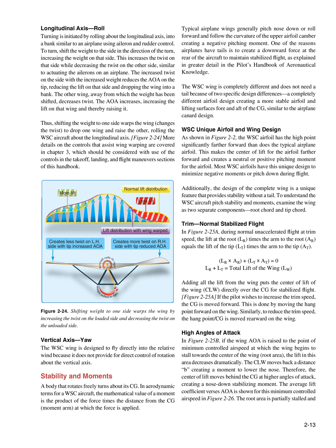Vertical axis, yaw. The WSC wing is designed to fly directly into the relative wind because it does not provide for direct control of rotation about the vertical axis. Stability and moments. A body that rotates freely turns about its CG. In aerodynamic terms, for a WSC aircraft, the mathematical value of a moment is the product of the force times the distance from the CG, moment arm, at which the force is applied.